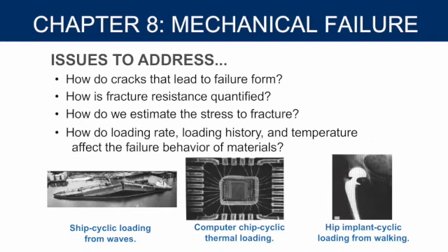We're also going to talk about how we quantify the fracture resistance of materials and how to actually estimate when things can fracture. And then we'll go into how things can be loaded if we put a stress or force on something over and over again repeatedly. That can cause these cracks and voids to propagate, and once that happens, the material will eventually fail. This could happen at much lower stresses than if you tested the original material in an Instron machine. If you cyclically load it over time, it can fail at much lower stresses.